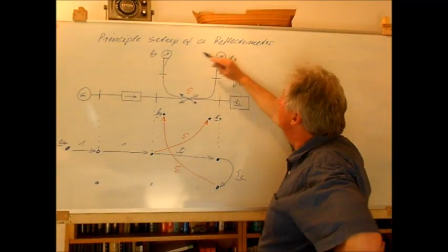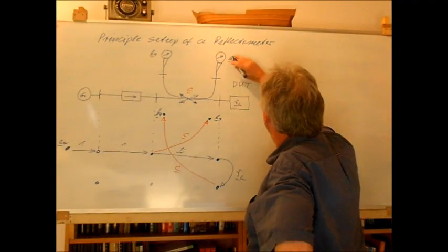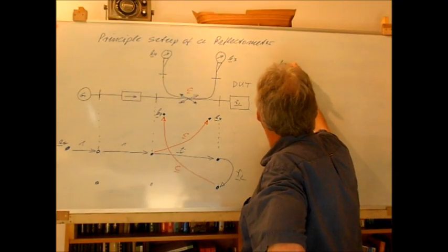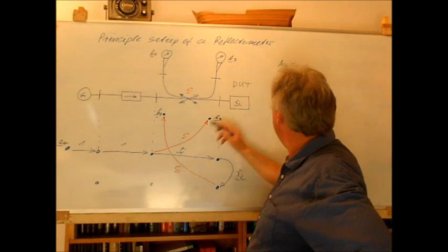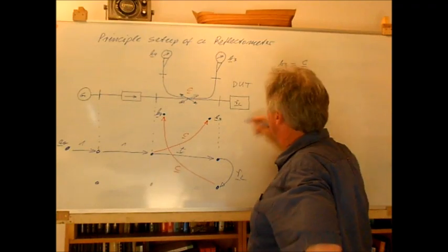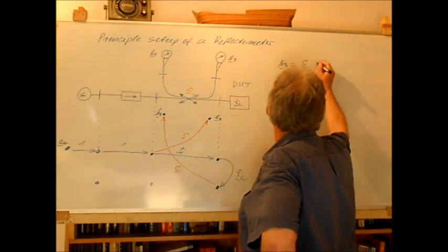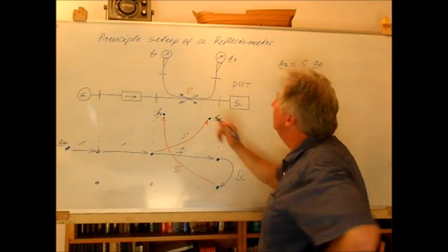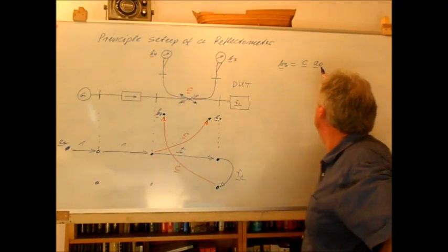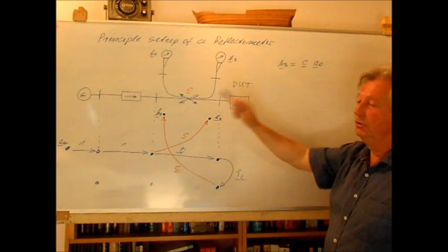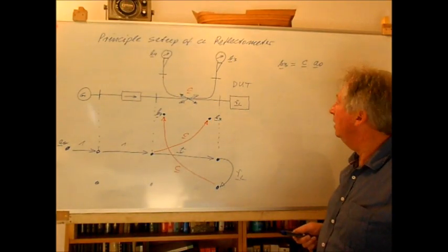So in principle you can see we can easily calculate the wave amplitudes. I assume here we could measure these wave amplitudes. So we would measure B3. According to this, B3 will be C, the coupling coefficient, times 1 times 1 times A0. So the wave amplitude B3 will be proportional to A0, the wave amplitude generated by the generator.